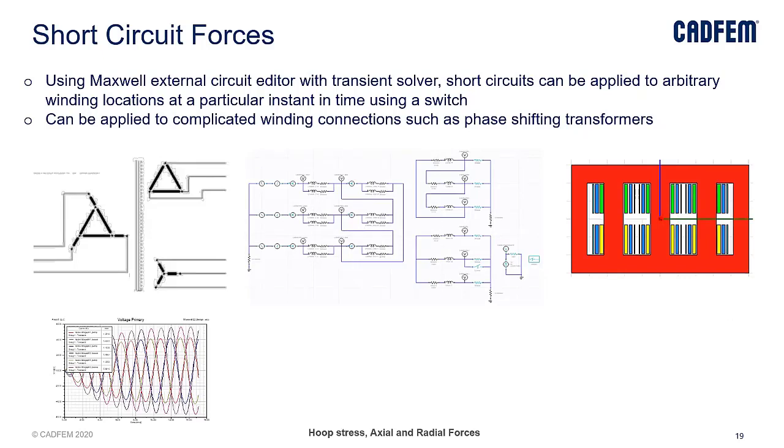In the simulation, we create the setup for whatever switching condition you would like to test. If you would like to short circuit the winding at a particular time, you can do that by creating a shunt switch across that particular winding with respect to the ground, and set up that kind of testing.